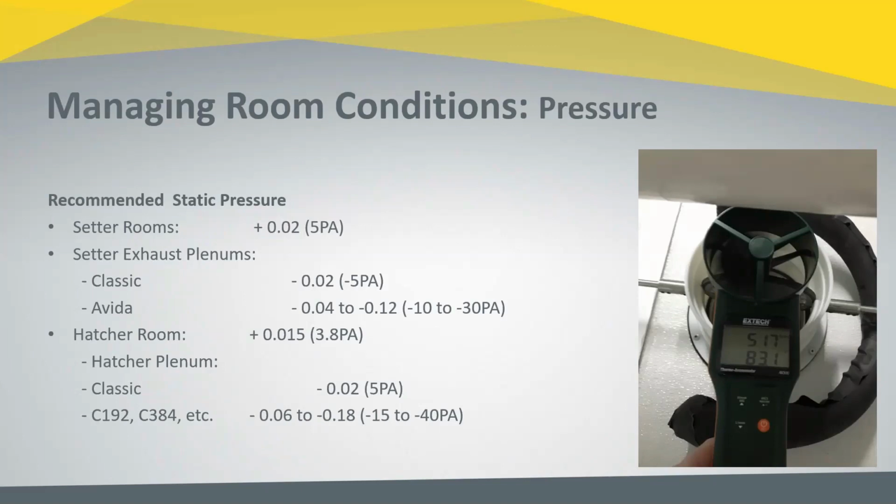And then with the aux fan on, that's where you want to be capable of achieving up to the 10 up to the 15 CFM per 1,000 range. So you want to take that as a two-step process. Measuring it without the blower verifies that you're capable of moving adequate air for oxygen demand and to deplete CO2 without the blower. But then when the blower comes on, you just want to make sure that you're not overwhelming the machine with too much air, but then you want to make sure that your auxiliary fan is being effective. Okay.